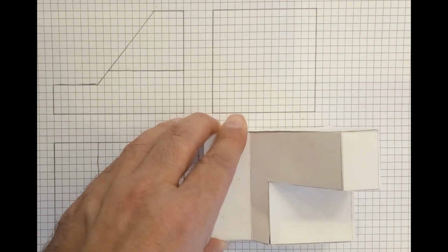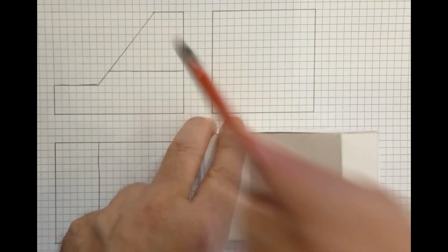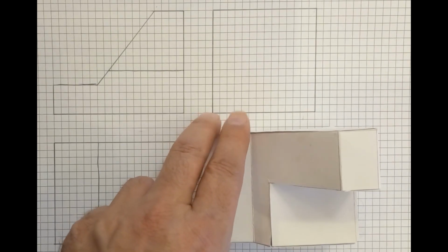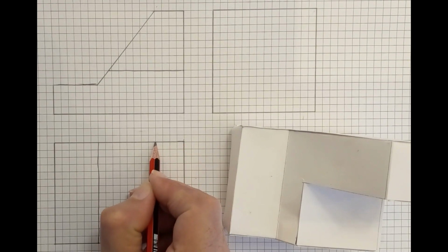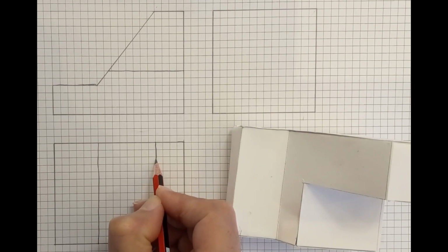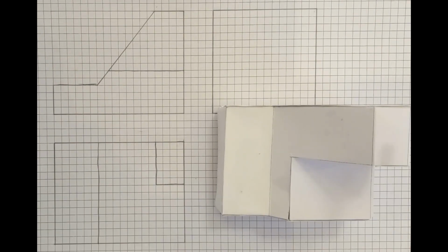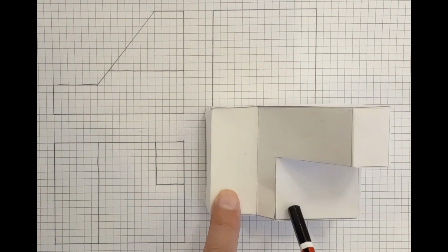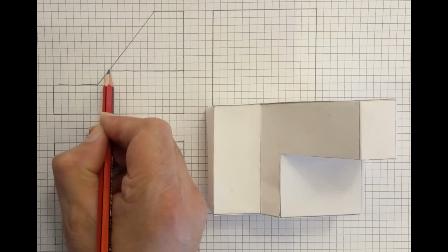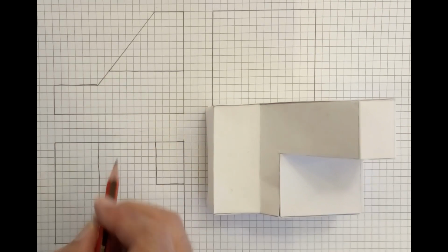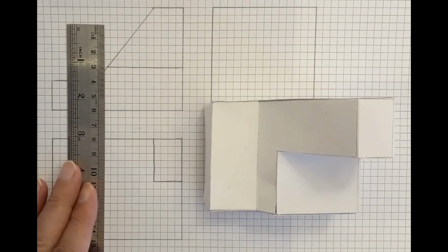I will start with this one. This rectangle has a dimension of 20 millimeter, the same as this length, and the other dimension we will get from the drawing. From the drawing it is 30 millimeter. So from this corner I will go to the left by 20 millimeter, then go down by 30 millimeter, then make a horizontal line like this. So this rectangle represents this one. For another rectangle here, this edge is represented in the top view by this line, by this point, sorry. So aligned with this point, I will go down like this.